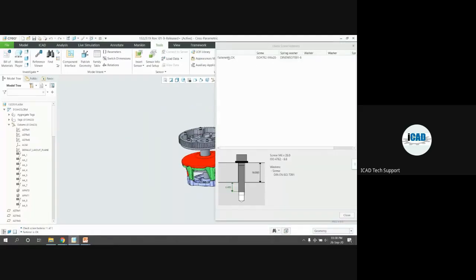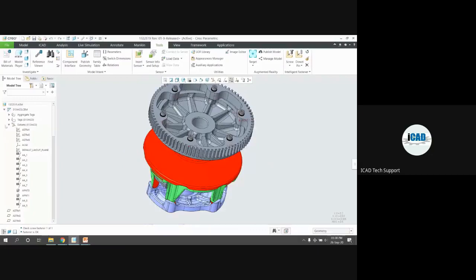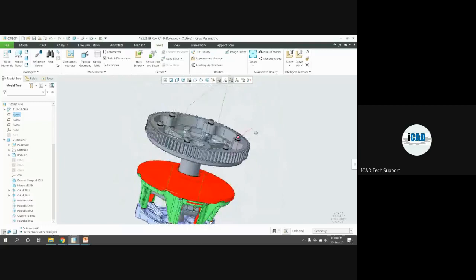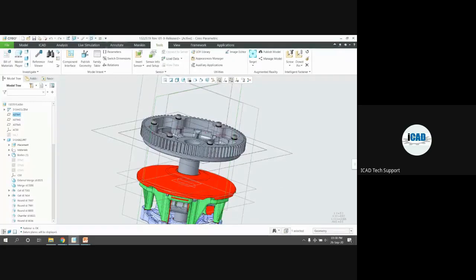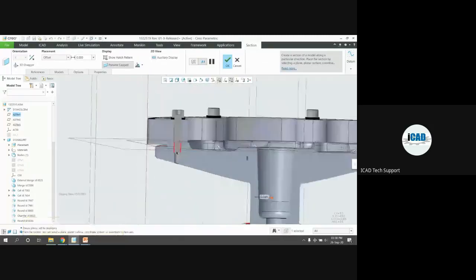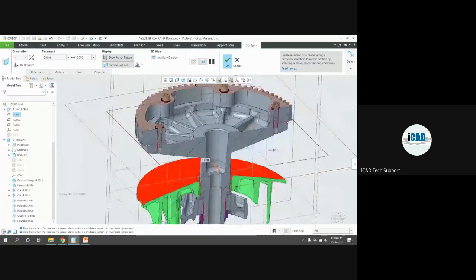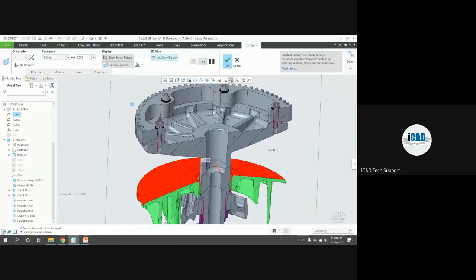You can see now the fastener is okay. If I want to check the preview for it, I can also cross check by using this section window. You can see here in the section window, here is the hatching. I am applying it, disabling this to auxiliary view. This is the auxiliary view, also available for the 2D preview of our section.